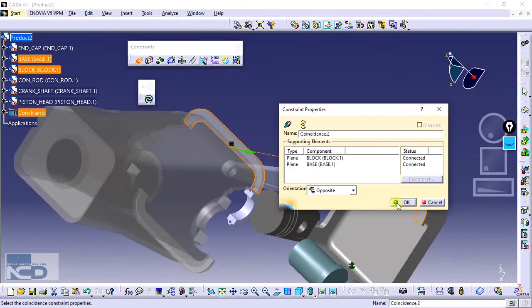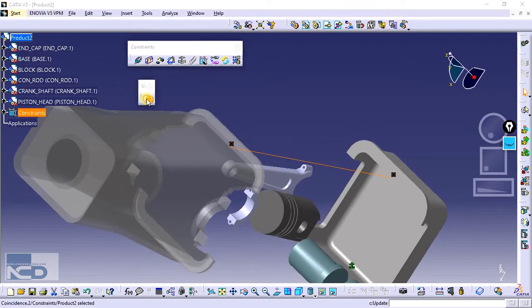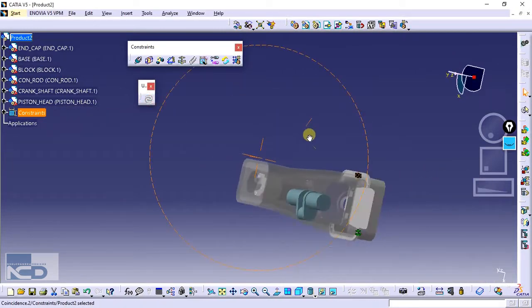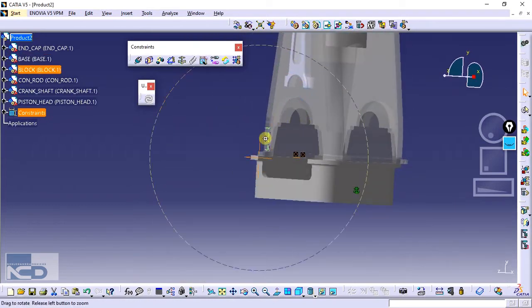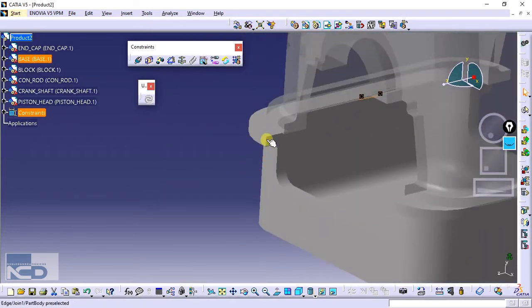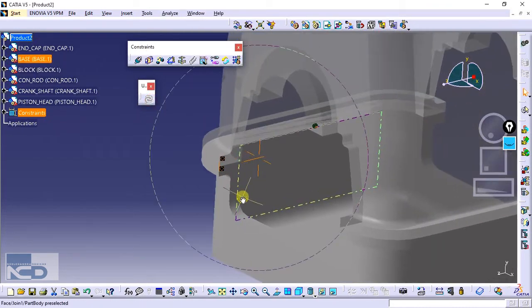and then just make it okay and update your project. You can see that the body is now attached. Then over here you just have to make these sections coincident. So go for the coincident and make this edge and this edge coincident. What this will do is align this whole thing together like this.